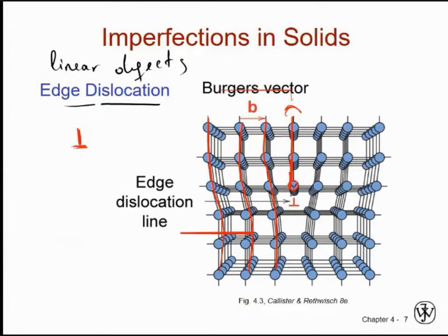If you see these circles behind it, or look at this here, if you can count atoms, this one has another atom behind and another behind, so it is a line of atoms. I have the same thing over here. All this line of atoms here will be the dislocation line. So the end of this half plane is the dislocation line, and this T points toward it.